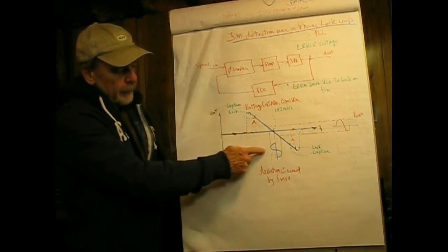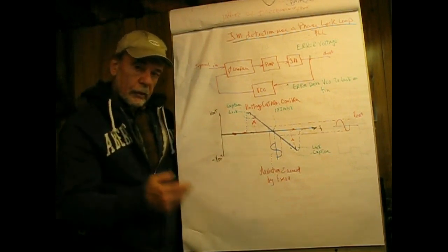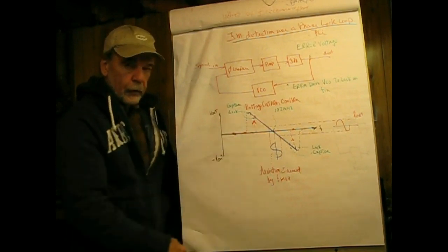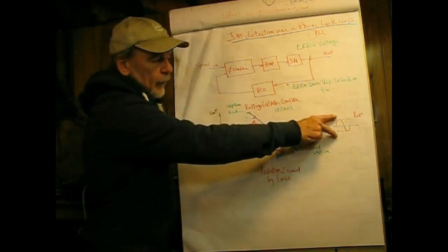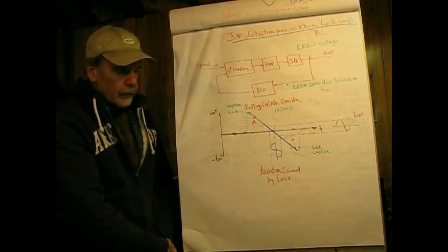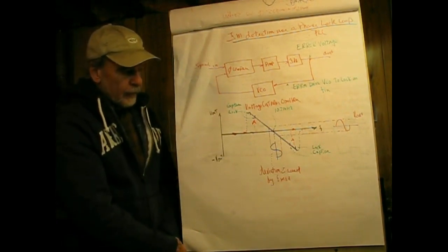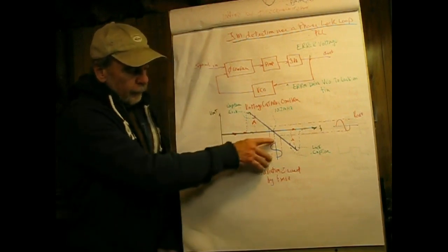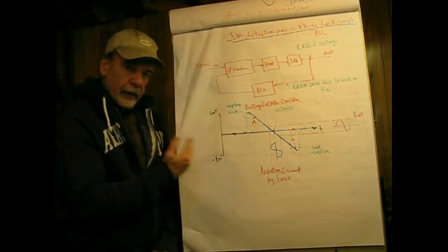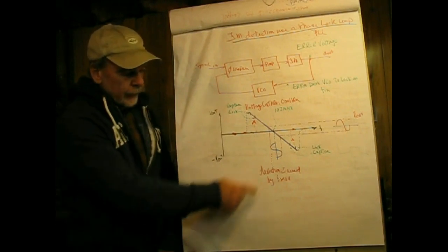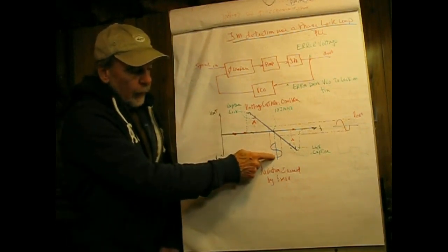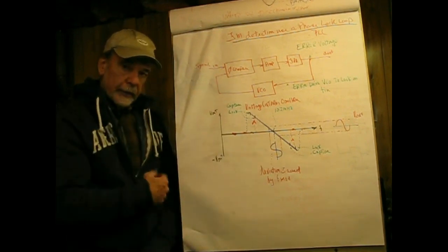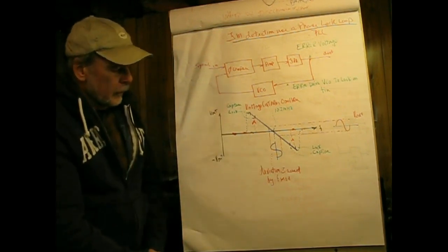So, as you can probably imagine, if we increase the magnitude of the modulating voltage and do that projection off of the VCO characteristic, we'll see a sine wave out here which is larger in amplitude. So, the amplitude is a function of how much the carrier signal is deviated. The frequency is how fast it's deviated back and forth. 2 kilohertz deviation, we'll say, would have one complete sinusoid inside of a half cycle of 1 kilohertz for deviation.